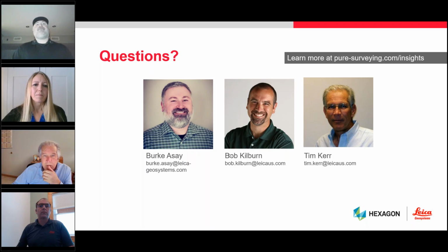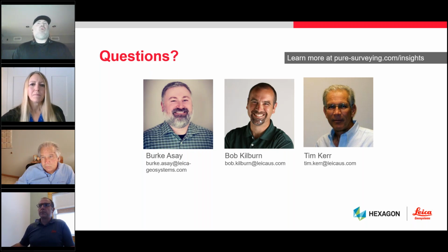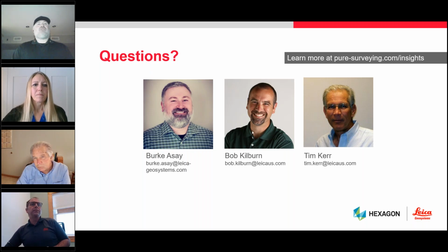Right. Okay, excellent. The small surveys done with the photos, like on your stockpile, are there speed issues if you're using the CS20 controller, the handheld controller, versus the tablet? What would be the differences in that regard? Yeah, so the CS35 has more computing power, so it is quicker. I don't have the exact numbers, but I would say it probably takes about twice as long for the storing of the data using the CS20. So the CS35 is probably recommended, but the CS20 does work and it is effective. It just takes a little bit longer out in the field.